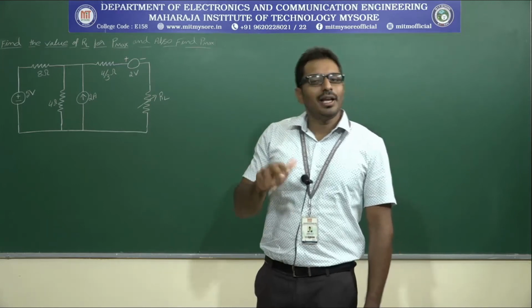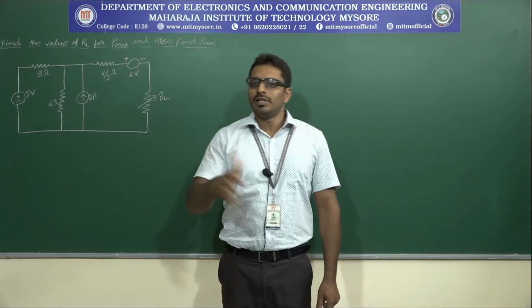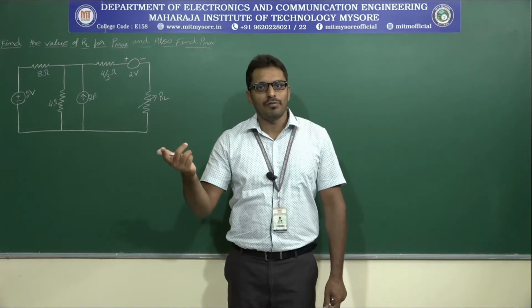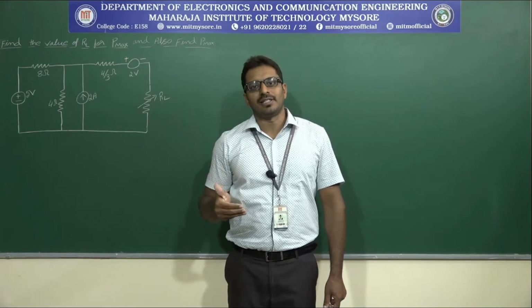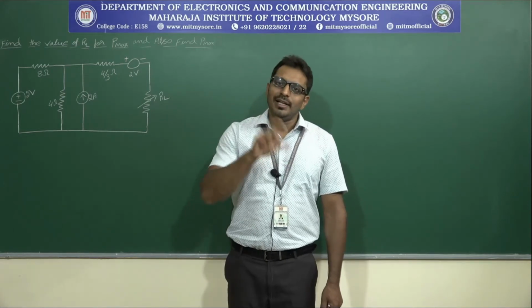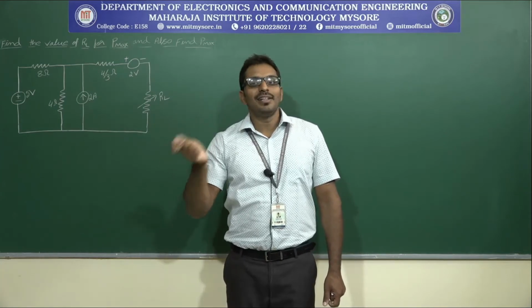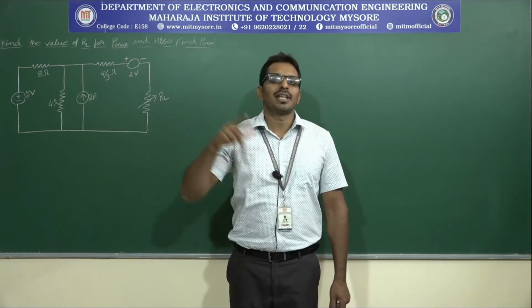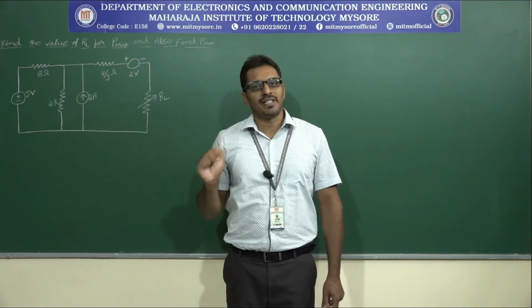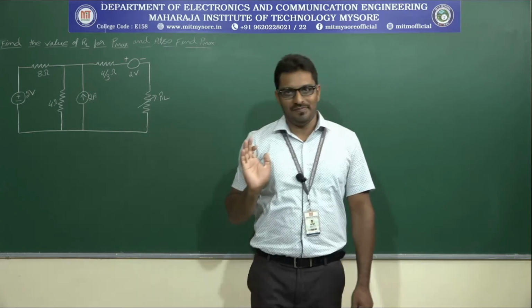By knowing the type of source and type of load, we can decide whether it comes under case 1, case 2 or case 3. In case 1, a DC source is connected to a variable load resistance, RL is equal to R0. In case 2, an AC source is connected across a variable load resistance, RL is equal to the magnitude of Z0.